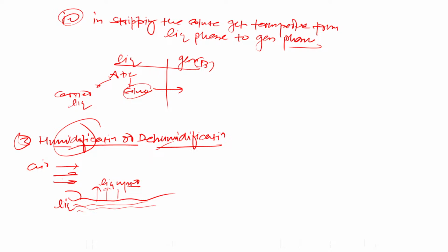And this air is moist air because it consists of more than one component. It's not pure air. It's air plus moisture. Clear? So carrying of liquid vapor from the pure liquid into the gas is called humidification. One very important thing about humidification is that the liquid phase is always pure. It means the vapor transports from its pure liquid state into the gas. That's called humidification.